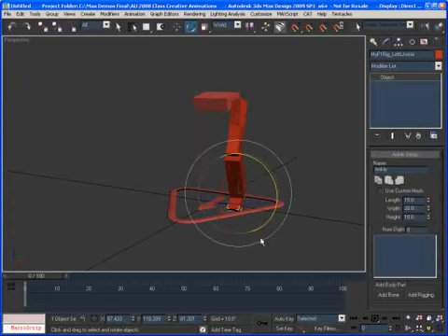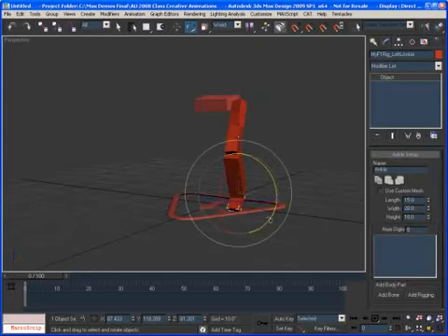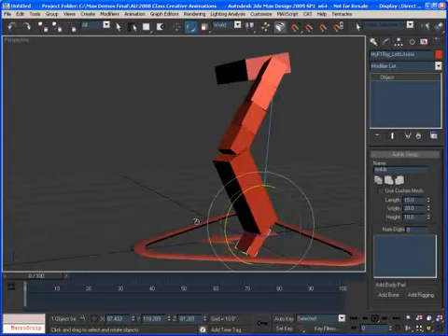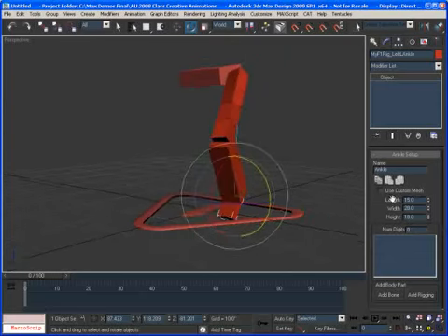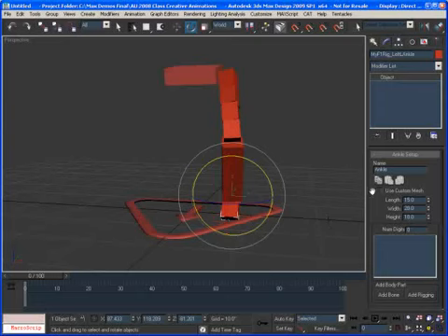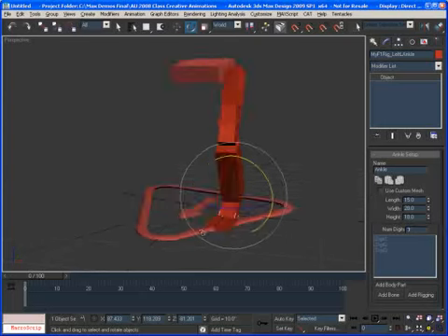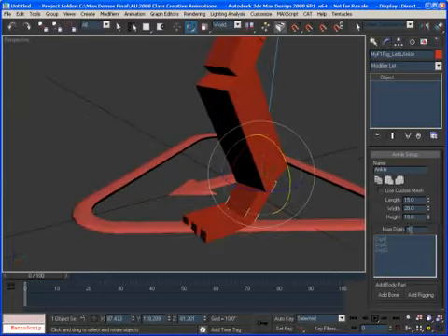What I'm going to do now is I'm going to grab the ankle. The ankle has specific features. You see that it's still part of the leg, but it has a specific set of settings. The reason is that from the toe you want to build digits or toes. So the ankle here, I can turn on a number of digits. If I say we want to have 3 toes, just say 3, and now we've got 3 toes. If I want to have 5, just go 5, and we've got now 5 toes.